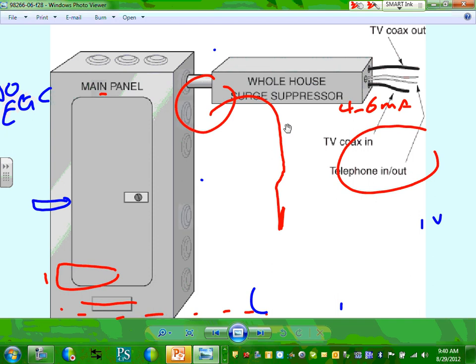They're going to require every main service entrance panel to have a surge protective device right at the main panel. Right now, this is industry standard on engineered projects. Every engineered project I've worked on, they put a surge protective device in the main panel to protect the whole building. We also go downstream and put surge protective devices in downstream panels. So in 2014, the coming code, they want to put this in the code.